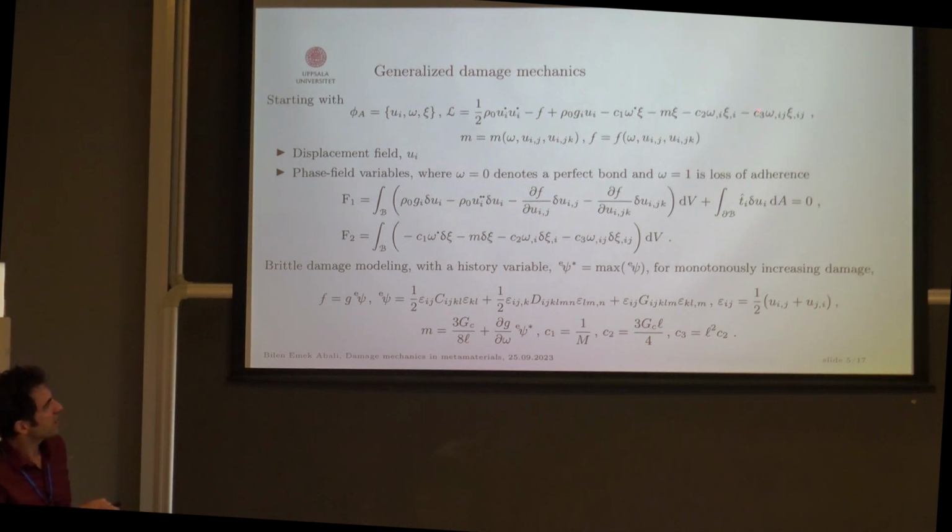Now the second derivative, which is a bit of a challenge, I'm combining it with this first derivative in order to make the number of parameters one less. What I have here is an L. L is the characteristic length of the thickness of the fracture. So 2 times L is the thickness of the fracture, which has a direct relation to the mesh, and I will get rid of the mesh dependency by using this one in the Lagrangian system.